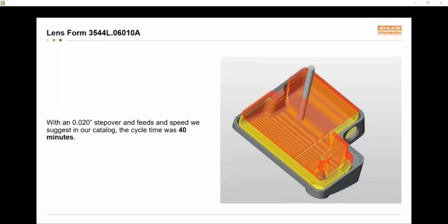And then the inside, so we tried to get a taper form or an oval form to work inside here, but because of the walls, the exterior walls of this part, we just weren't able to get it in there for it to make sense to actually use that tool. So we used a lens cutter. This was a 6mm shank with a 10mm cutting radius.